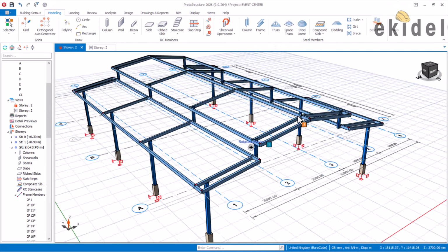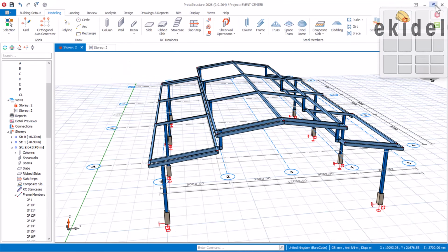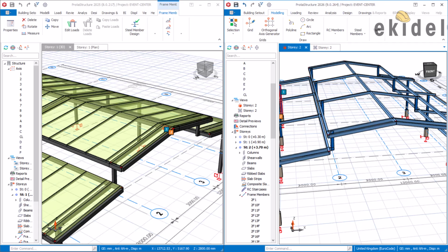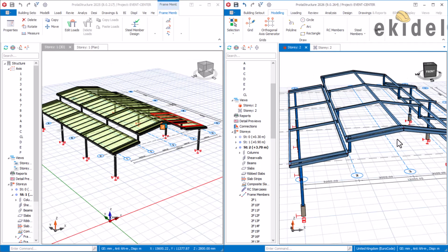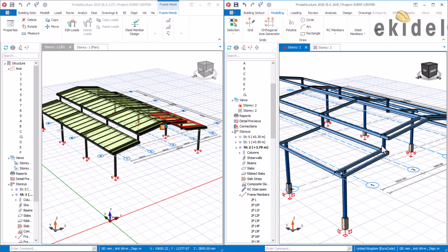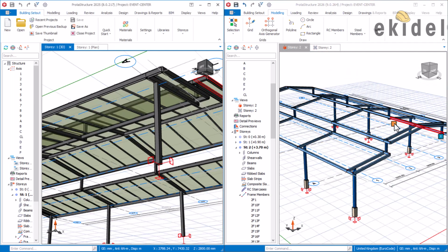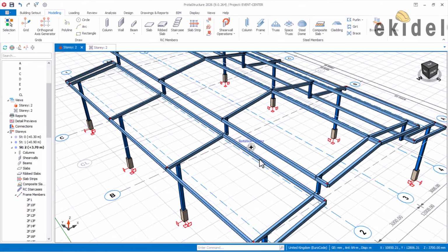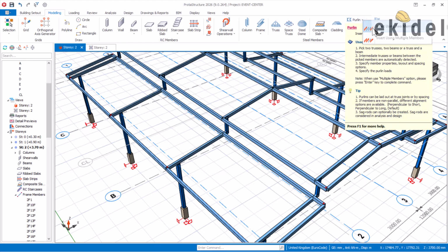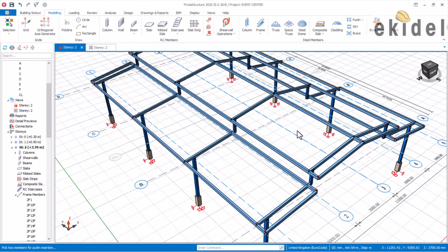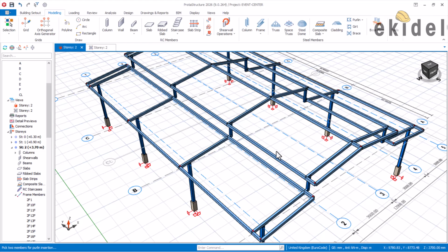The next thing now is our Purlin. So if you check that now, we have modeled this successfully. Everything has been added. Okay, so we can then model our Purlins now. Let us go down to this place and then click on our Purlin here. Sorry, on our Purlin here. And then click on this Purlin here, and on that note we click on the first beam and the second beam here. Okay, allow it to display the Purlin property dialog box.